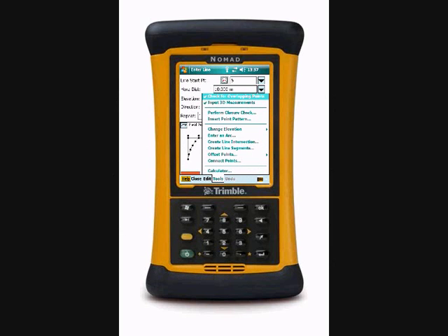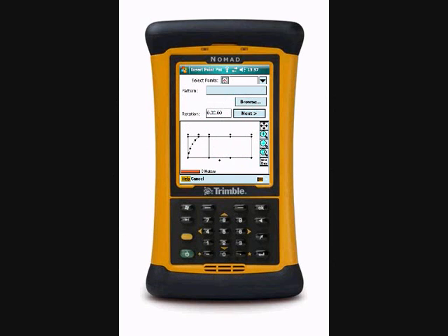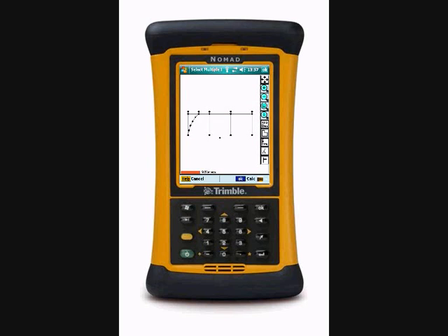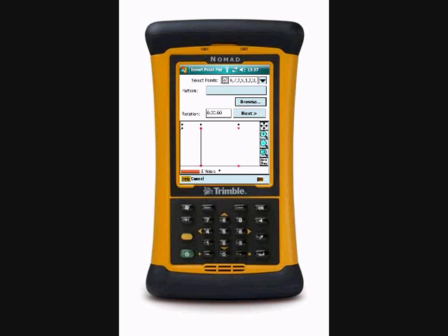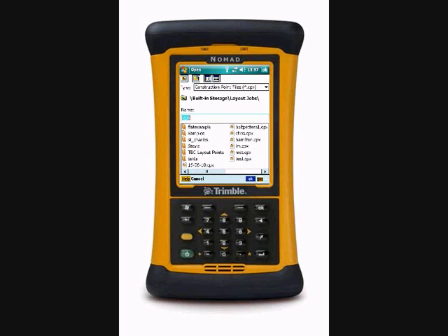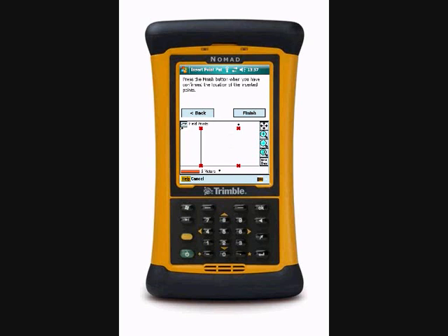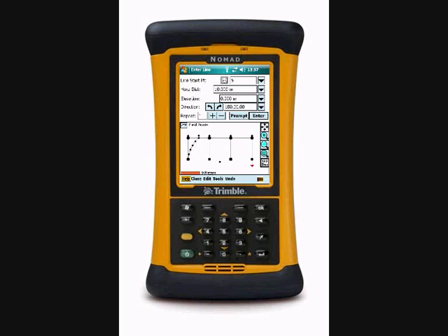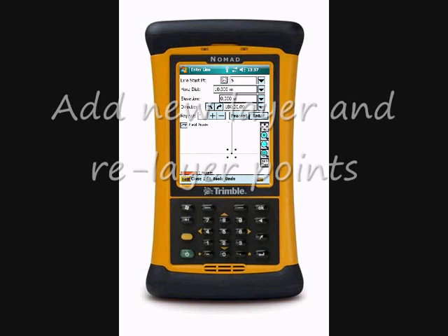Back into our master plan, and now we just select the points where we want to apply the point pattern. So if these were bolt sets, this could be column locations. Very simply, just point and click off the screen, nice graphical interface. Choose all the points we're interested in, load the pattern we've just created, just find it from the list wherever we've decided to save it. Gives us a preview, and when we select finish, we'll see that it's automatically added these point patterns on here. So very quickly, simply, if it were bolt sets, it's perfect.